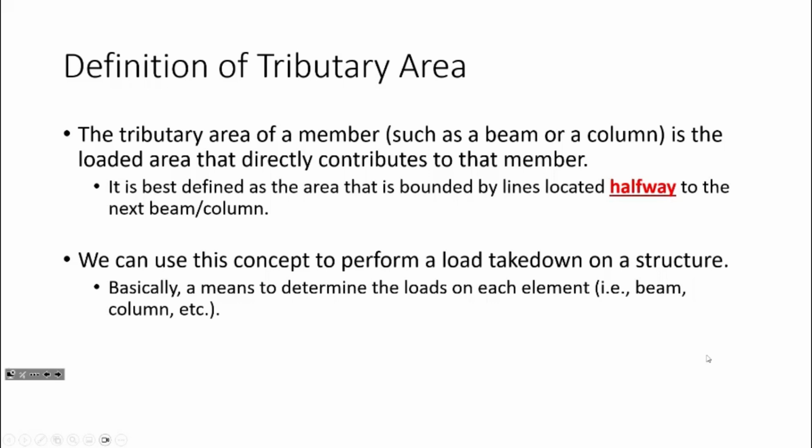Okay? So for example, if you look behind me, I've got a column right here that is supporting the external facade on this side of the building. And I also have a column right here. So I'm imagining, I don't have the floor plans with me, but let's say we have a beam from this going this way, and we also have a beam right there. So let's just look at this beam right here. The tributary area for this beam is going to be all of this halfway over to this one.